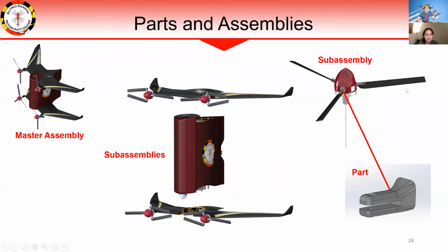In this case, the rotor sub-assembly appears 4 times on these other sub-assemblies. So if we just make one, we can import the sub-assembly into this project, and then everything else comes together in the master assembly. If you're smart about setting up your workspace before you even start CADing, you can do really complex projects later on down the road.